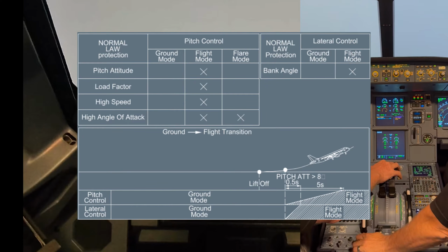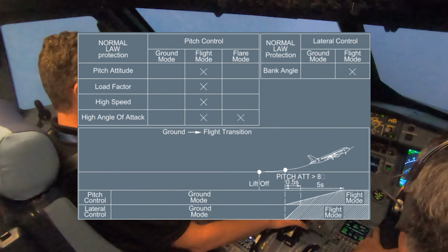Even in flight mode of lateral control, abrupt rudder movements will result in bank. Try to minimize rudder movements, or if slight rudder correction is needed, be prepared to apply a small bank correction in conjunction. In addition, be cautious of pitch inputs that may lead to over-rotation or neutralizing the side stick before being in pitch flight mode. This could lead to your nose coming back down since the aircraft has not finished trimming.